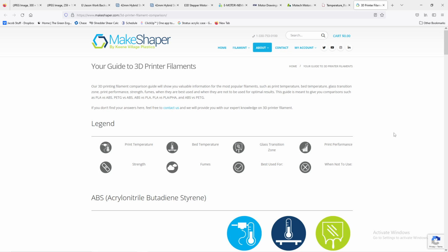But there are limits, and those limits are your design of your printer. If your printer was never designed to be put inside of an enclosure, and that is what type of stepper motors does it have, what is the insulation class rating, what type of cooling systems do they have, what type of airflow inside your printer, how long is your stepper motor, what kind of stepper drivers and stepper settings does it have, etc. Right? And those can be remedied by increasing the length of the stepper, increasing the temperature rating of the insulation, such as the LDO high temp steppers, changing the stepper settings or changing the stepper drivers,